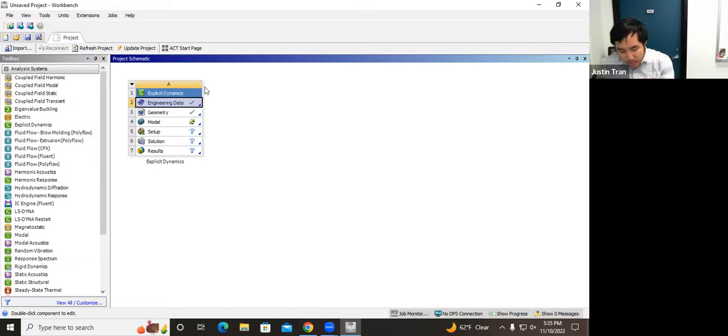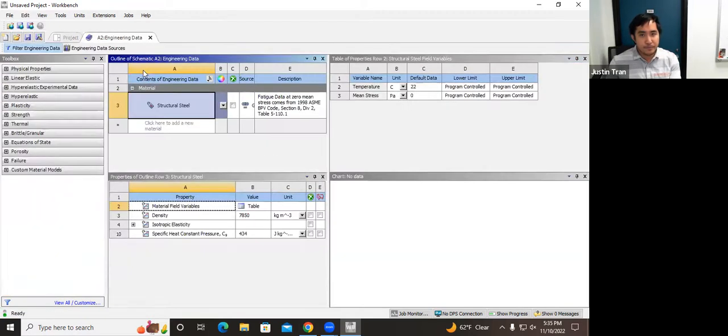All right, one other thing that we're going to do before we jump into ANSYS Mechanical is we're going to add some material properties. And so we're going to double click on engineering data. Okay. And so when you double click on engineering data, you'll see that we have structural steel here. Okay. And so good old structural steel. So our usual one. And so before, when we've added a material, we've kind of, I would consider, added from scratch. But ANSYS actually has a material library here that I haven't told you about before because,